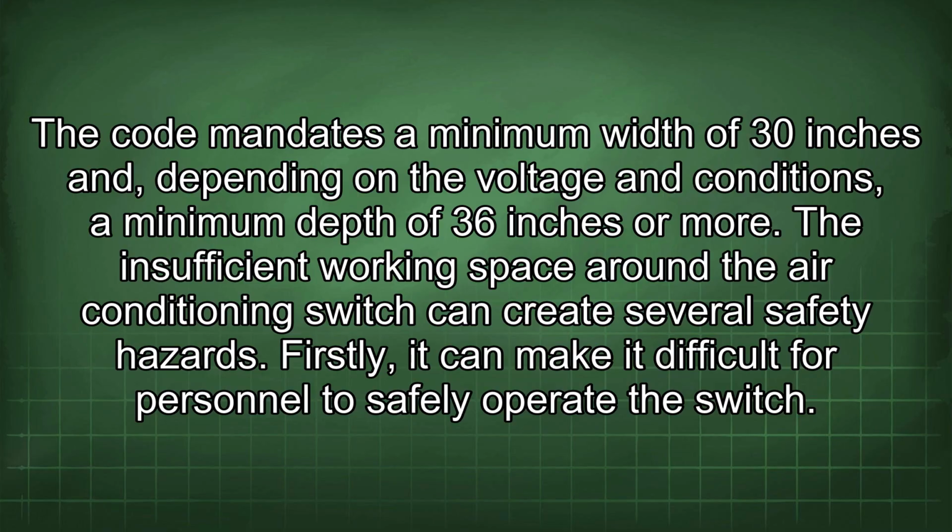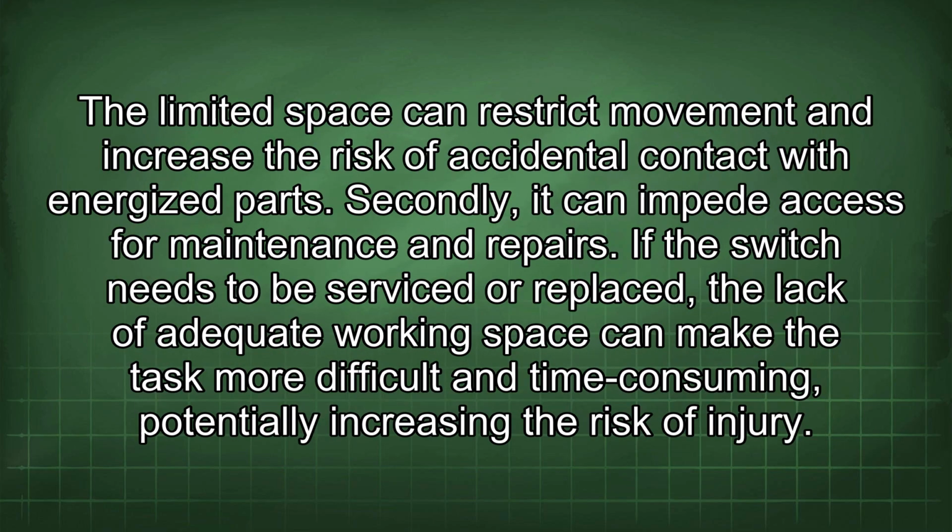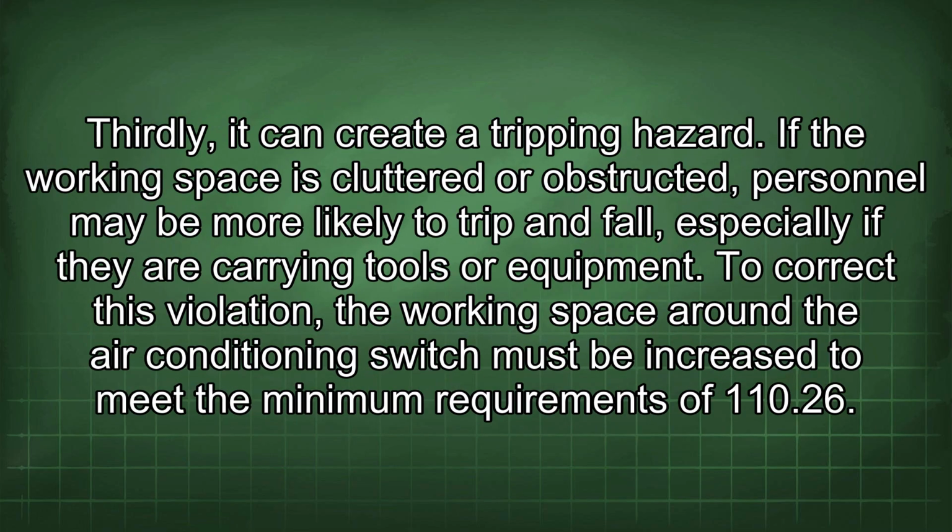Firstly, it can make it difficult for personnel to safely operate the switch. The limited space can restrict movement and increase the risk of accidental contact with energized parts. Secondly, it can impede access for maintenance and repairs. If the switch needs to be serviced or replaced, the lack of adequate working space can make the task more difficult and time-consuming, potentially increasing the risk of injury. Thirdly, it can create a tripping hazard. If the working space is cluttered or obstructed, personnel may be more likely to trip and fall, especially if they are carrying tools or equipment.